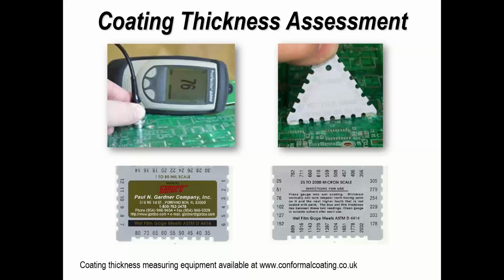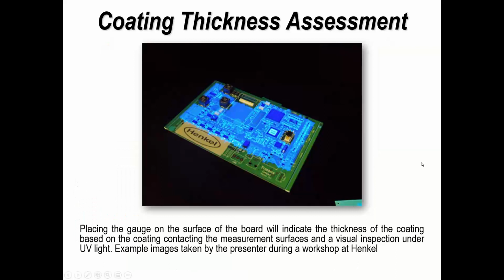It's a gauge that's basically working by eddy current. So you're looking at the surface and how far that is away from a metal coating on the base of the printed circuit board. And we check it with calibration slips to make sure we're getting an accurate reading. But that's for dry, so it's after curing. Now, again, that's a sample check on a flat surface, not on component terminations. But if you were to do that as a regular check, it's better than not doing anything.